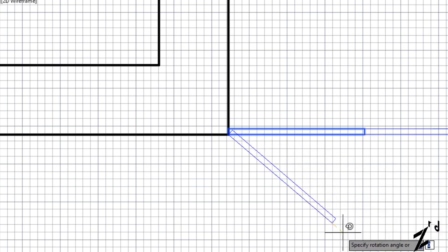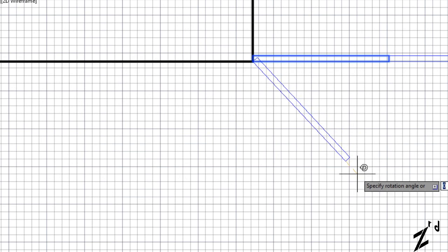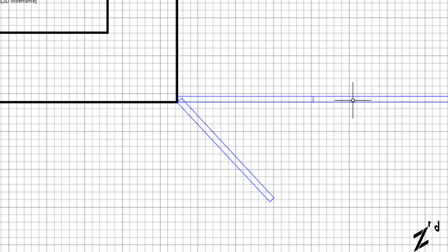Take off F8, so it turns around there, which is all good and nice. So that stops there. Another rectangle for the second door, rotating about that point. Again, take off F8, so that opens, and then a rectangle along this point, and rotate about there.